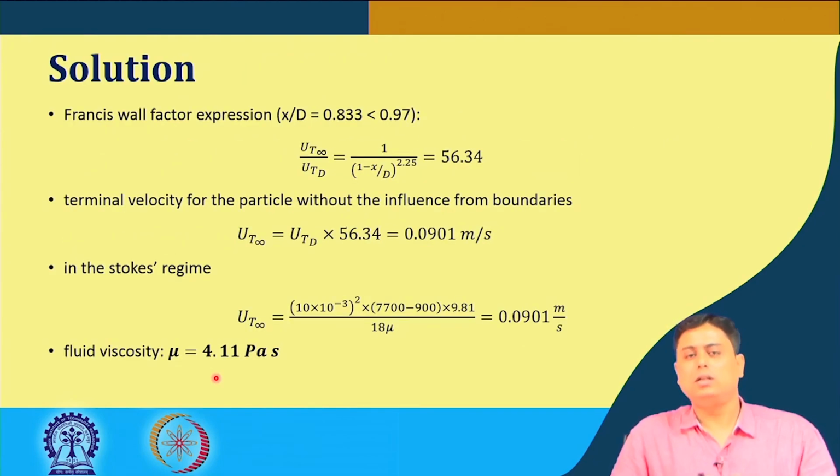Since the dimensions of the falling object and the fluid container are of similar magnitude, we had to correct the measured value by a factor, the wall factor, the influencing factor, for an infinite pool of liquid.